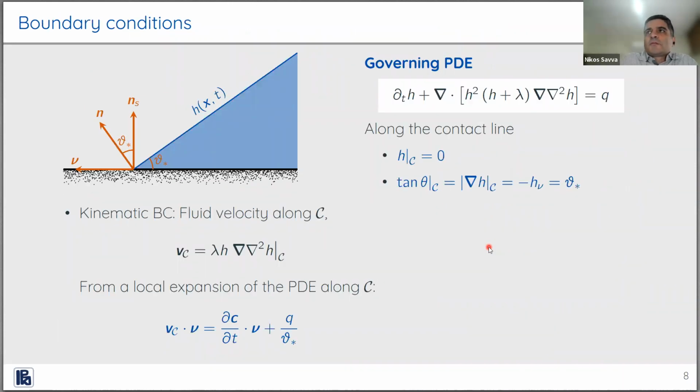So if we do all this, take these equations, the remaining terms, and put them together and use the appropriate boundary conditions, we end up with a governing equation for the evolution of the thickness h. Instead of solving for velocities, pressures, and the surface profiles, for example the liquid-gas interface, we only have an evolution equation for h. So this is a fourth-order partial differential equation.